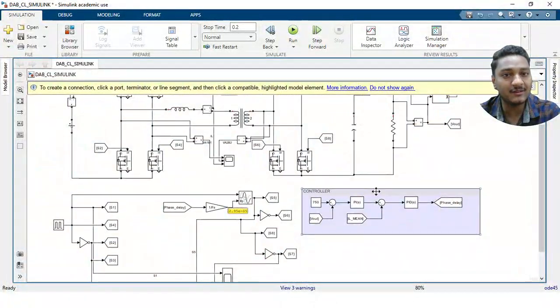because even when we design the closed loop transfer function using an accurate model, and when we tune this PI value, we have some particular range. We can't say that my controller will work for 100 volt to 800 volt, or you have to make the system in such an adjustment that with changing input, the system should adapt to the change. The system should know that okay, my input has changed or my load has changed, my output has changed. Then I can choose the values of kp and ki from basically a lookup table. So for this particular output voltage I should have this value of the PI, for this particular output voltage I should have this value of the PI. That provision you can keep when you design the closed loop control in DSP or FPGA.